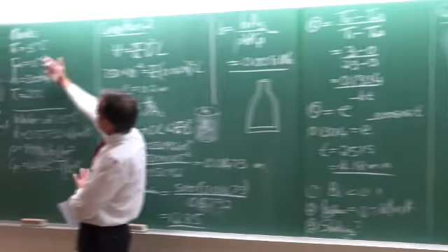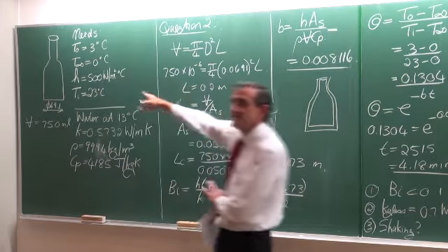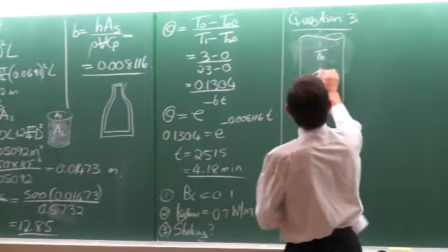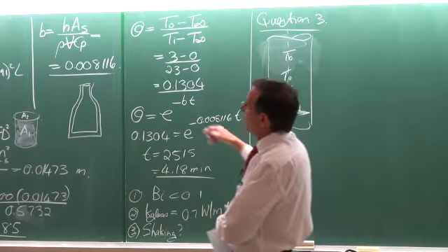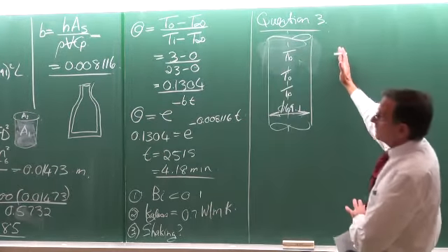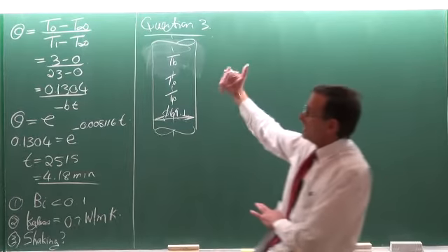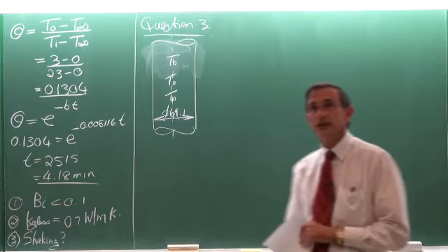We want to know how long it is going to be before the temperature is 0 degrees Celsius on the center. And take note, it is everywhere on that line, on the center. On the outside, the ice or the water is at 0, the heat transfer coefficient is 500, and now determine how long it is going to take.